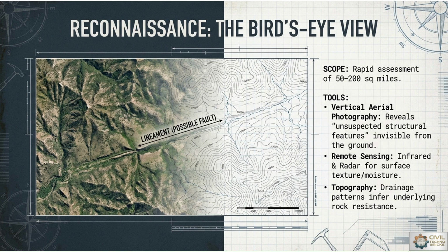With reference to that, we check the performance of any structure dependent on gravity or the rocky surface, which provides the strength and stability for supporting ground. For any dam and tunnel, geological conditions become even more critical because underground discontinuities may create seepage and instability. So what are the tools used for reconnaissance?